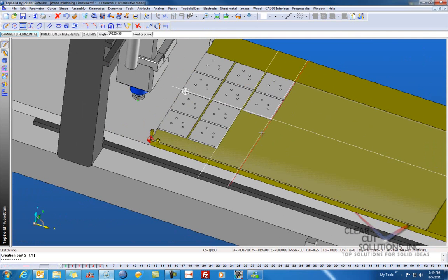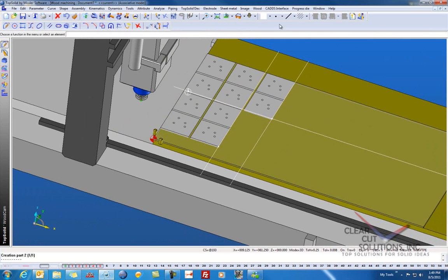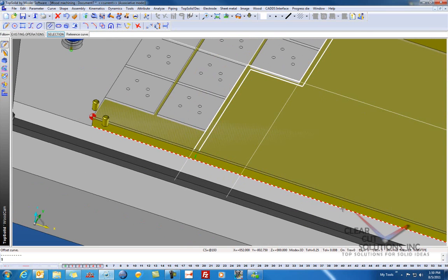Okay? And the reason maybe that I want to do that is so that I can easily create my construction geometry. So I can switch here to a thicker line style, and I can come here and trace down that, because maybe this is the path I want to take, right? Maybe you want to actually have a sketch line up here to trim this up to, whatever. You can trim it after the fact too. We can say trim that to this, why not? And trim this here to that. So now we have our exact profile we want. From there, we'll go ahead and offset that, maybe an inch. Okay? And that offset profile is the profile that we're going to actually cut away.